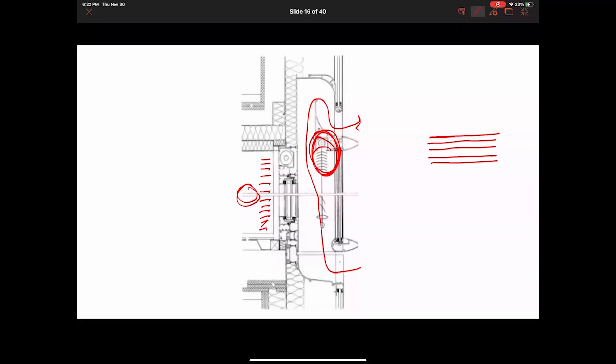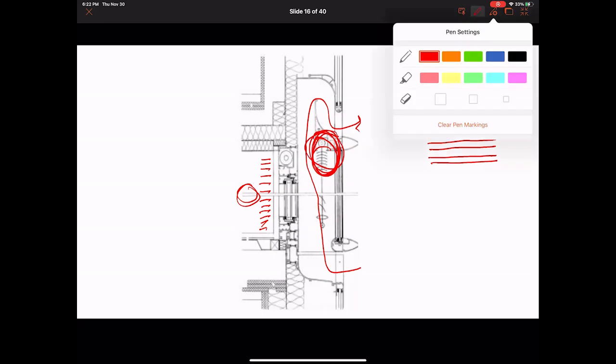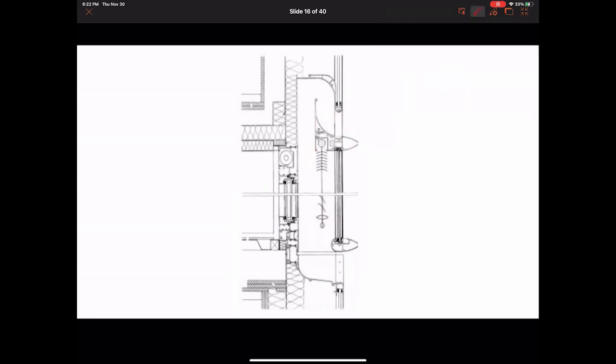The heat's already entered the space and it's trapped between the blinds and the window. You got it. It's pretty intuitive. So 80% is not bad, but not as good as outside. This is a good compromise because we can put the shades in the middle here, and then we can control them from inside, from a switch inside, and we can raise or lower the shades so we can provide our shading and still have control of it.